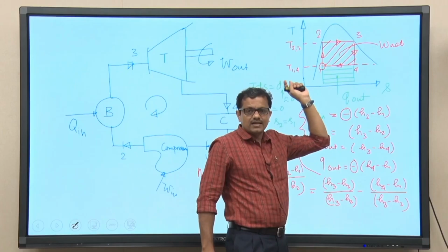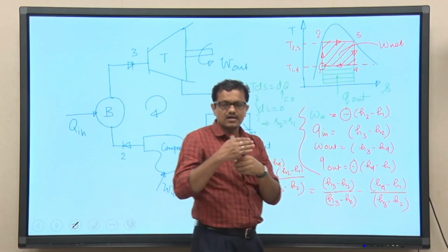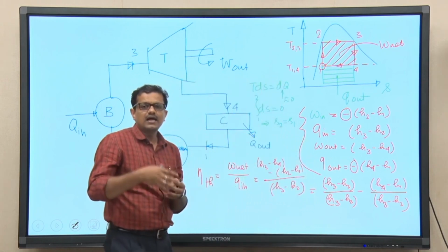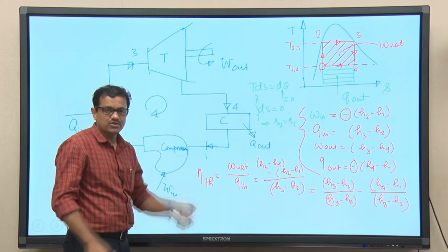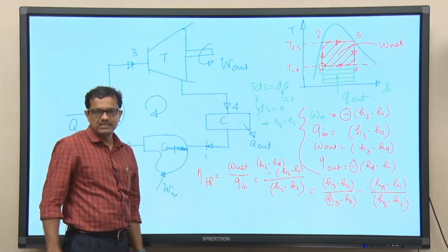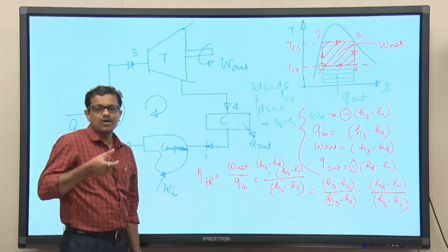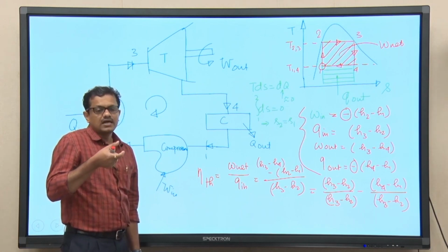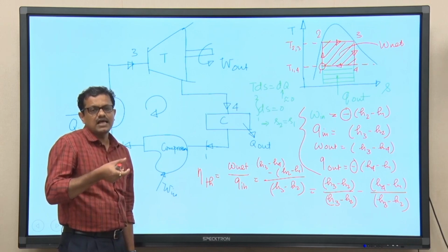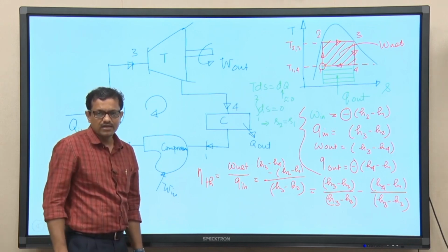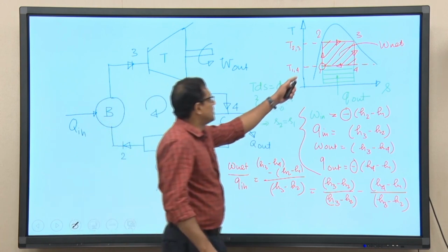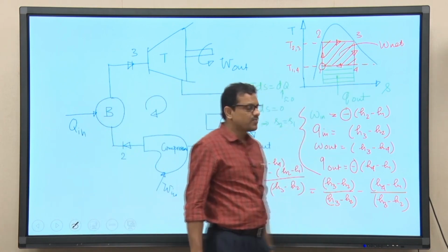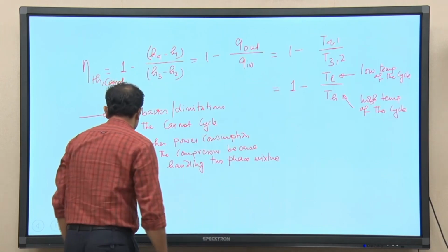Starting with a two phase mixture and terminating this process at the saturated liquid line is not so easy. So the design of a compressor which will take a two phase mixture as the intake fluid and eventually at the exit of the compressor we will be getting saturated liquid is also another issue.